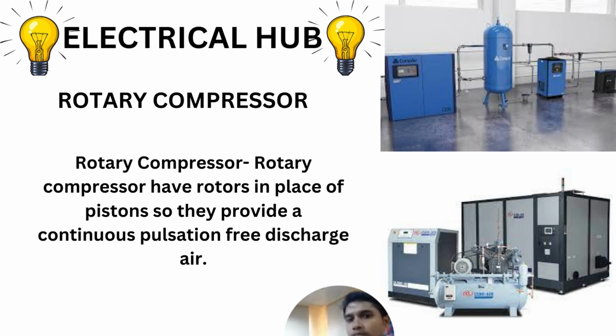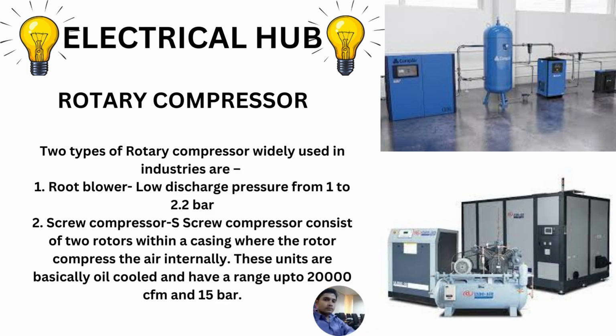Rotary compressors have rotors in place of pistons, so they provide continuous, pulsation-free discharge air, and they have a longer life because there are no pistons. Pistons are replaced here by rotors. There are basically two types of rotary compressors used in the industry. One is the root blower.